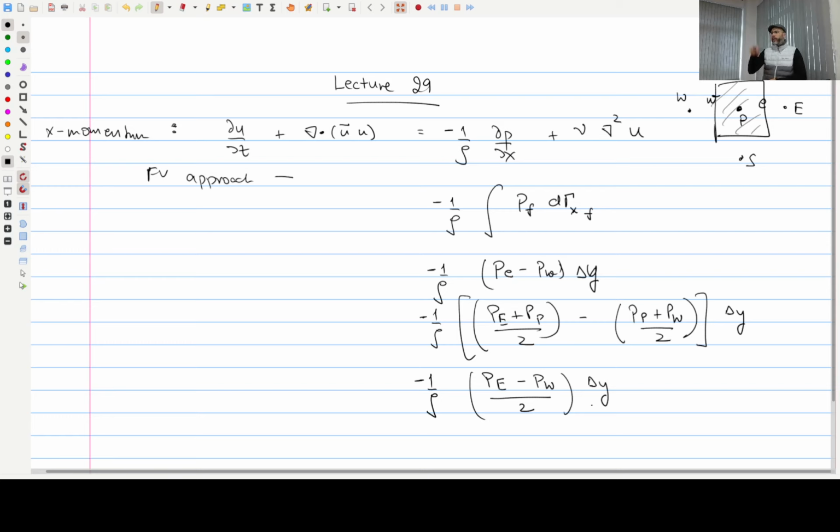There is no number that you reach and then beyond that you start getting accurate results. So for this we do something called a grid independence study. You keep refining the grid, and for finer and finer grids you look at the solution and see whether it is converging beyond a certain point. But that's a property of the problem. That's not a general guideline that can be used.